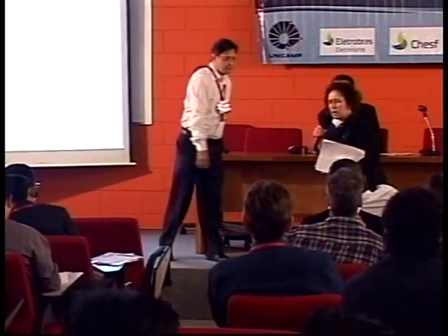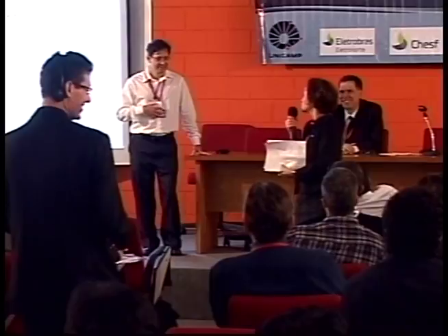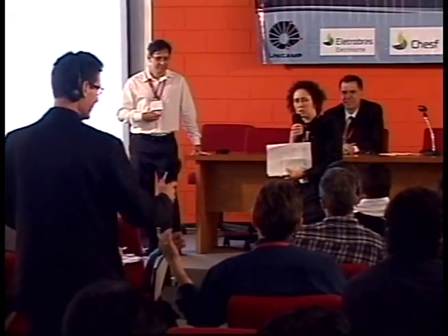I don't know if Cristina has something to add. The machine is represented by an ideal source behind an impedance. The representation of the machine is the same, the conventional model for transients. We are not representing the machine in this study. So the source through an impedance, then you have the transformer. The difference between the models is how the line was modeled. I'm sorry, I had imagined that the machine had something to do with it. Not in this case. Only tomorrow, when we are going to have a dynamic analysis. But for transients, we are only using one source.